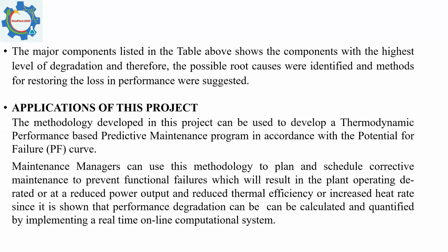We were only able to do actual calculations for about 3 months. It is very rigorous and demanding in terms of the challenges that were involved in using actual plant data, because most people know that actual measurements are not as accurate to do proper analytical work. Sometimes you may end up with a situation where there's no mass balance on a component, and of course, in accordance to the first law, we must have mass balance in terms of inflows and outflows.